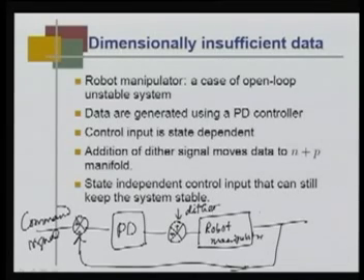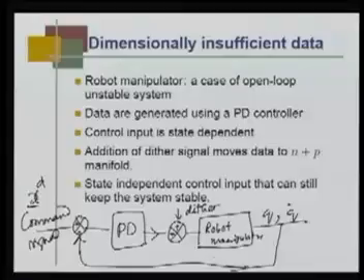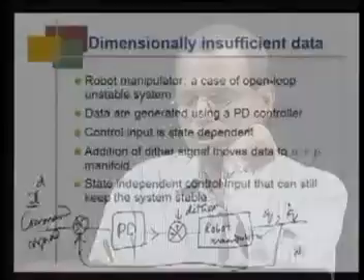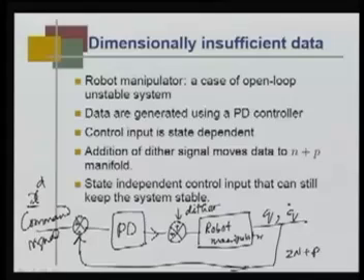So, the output of the robot manipulator, when we actuate the joints, we observe the link angular positions vector and angular velocity vector. They are fed back to the command signal, and the command signal is normally x desired, the desired trajectory that the links should follow. You have this PD controller. To the PD output, we add this dither signal just to make sure that the data being collected are not only spread over n dimensions, rather over 2n plus p.